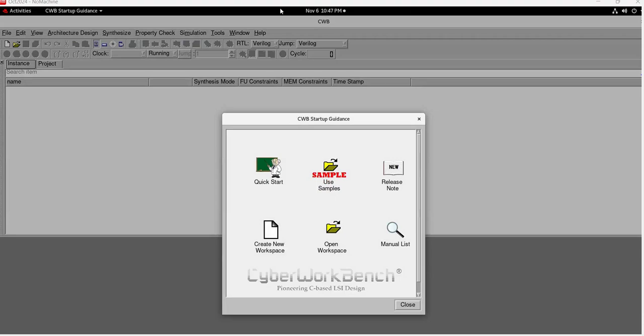Here we will learn how to use the commercial HLS tool targeting FPGA. We will use NEC CyberWorkBench to perform the three main HLS steps using the commercial HLS tools: resource allocation, resource scheduling, and binding. And we will learn how to verify the design works as expected, and learn how to use the automatic test bench generator and create an input file and perform RTL simulation.